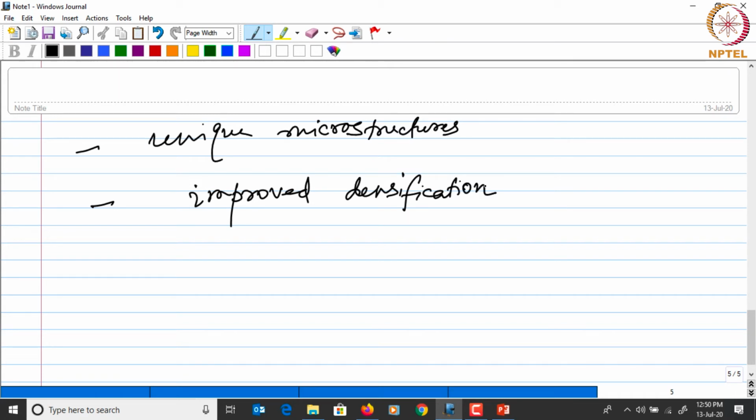Okay, so the idea of sintering is to actually densify the compact. So let us talk about how the densification happens in this case when you have two or more different metal powders mixed together for making an alloy. Okay, so here two things will happen. One is of course formation of the alloy, or the chemistry. So here homogenization is an important factor.